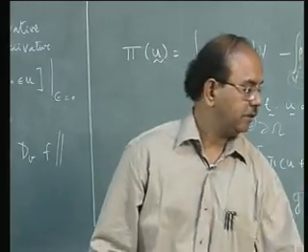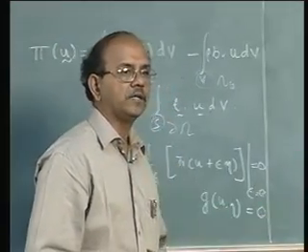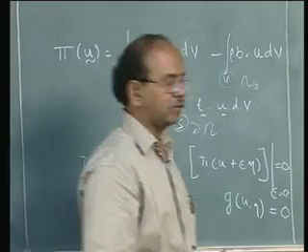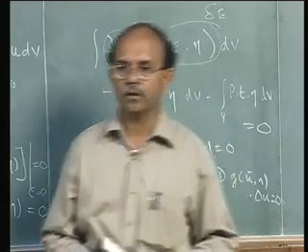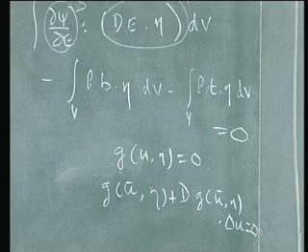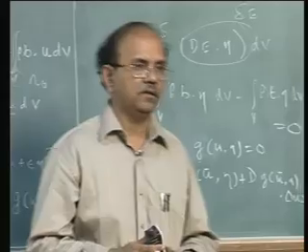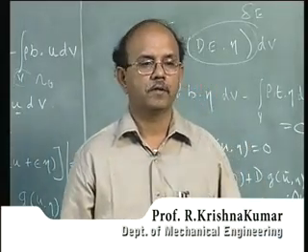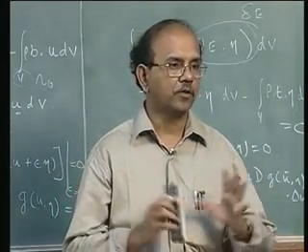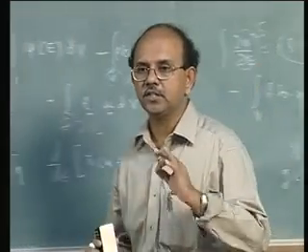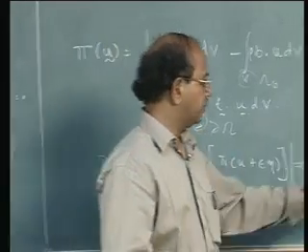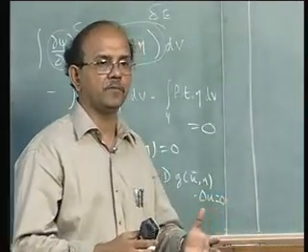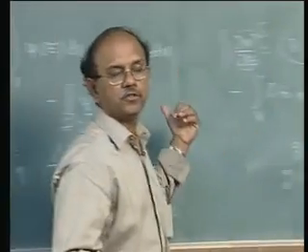We will go into the details later, but I just wanted to point out how we can develop the Newton-Raphson scheme as well with the directional derivatives. Now we will come back to this after about 4 to 5 classes and develop the Newton-Raphson procedure for this kind of large deformation problems. That, in other words, without any frills attached to it, just the displacement based finite element analysis, not mixed formulation or anything like that, can be developed straight away from here. Of course, if you want to develop mixed formulation, then the functional that you take is going to be different.